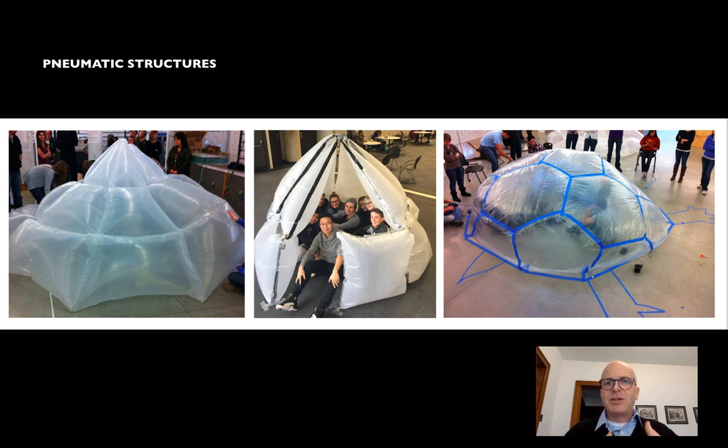We're pre-tensioning cables or fabric by injecting pressurized air into a system. And that air pressure, just like the dead load of the heavy roof cables, is going to make sure that membrane, that pneumatic membrane, is always in tension. And we're going to inflate it.